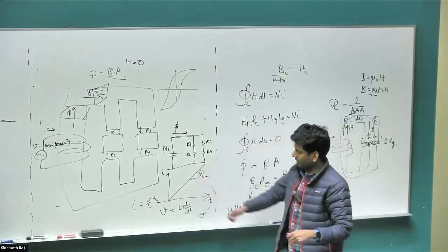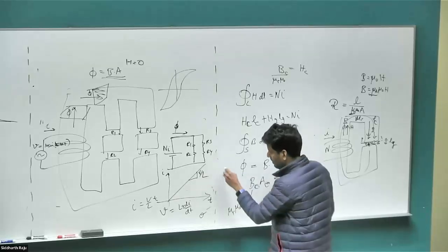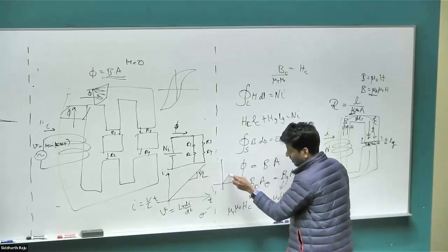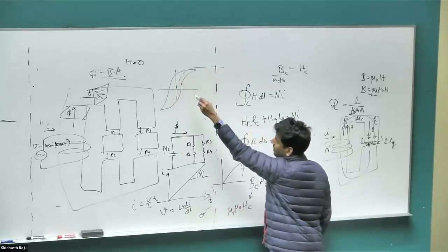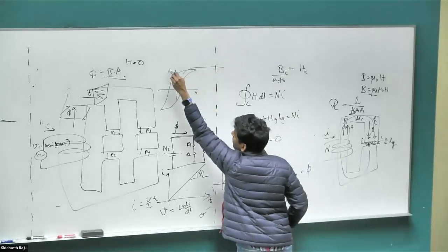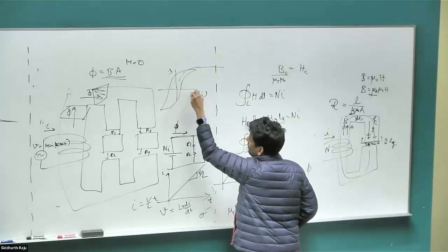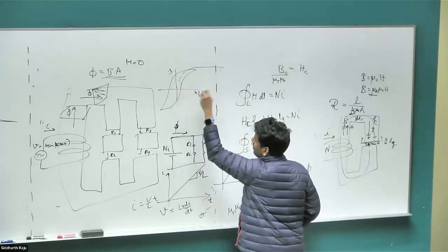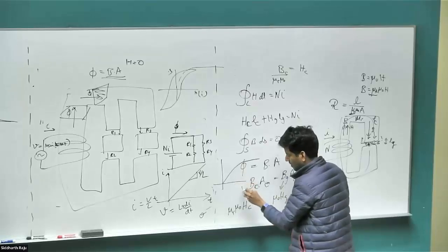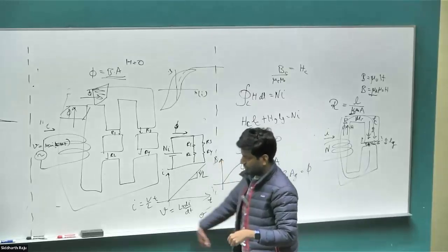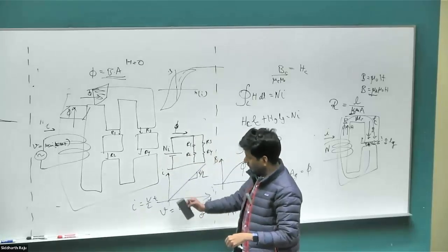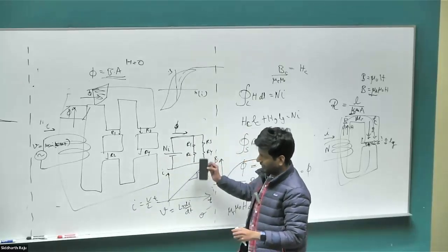So this current is going to keep on increasing, but your B field will initially start to increase linearly, and then it will saturate out, because that will be exactly that curve. This was H versus B, which is the same as I versus B. If you linearly increase I, that's just traveling along this axis, which is the same as increasing the B field. So B would end up saturating your core. For all of this, you need to know the inductance to figure out the slope at which the current is going to rise.